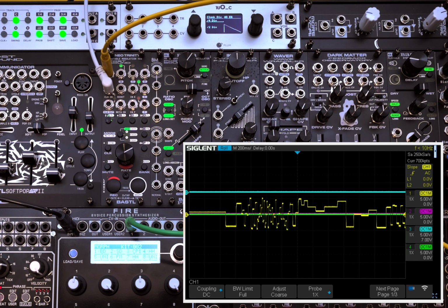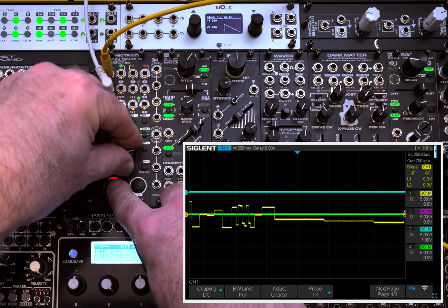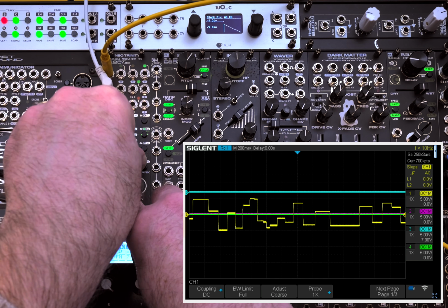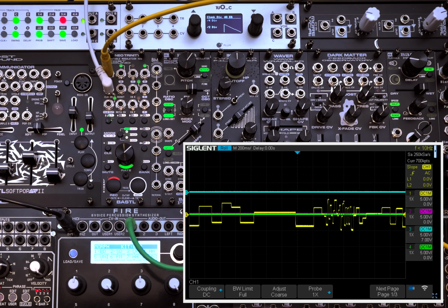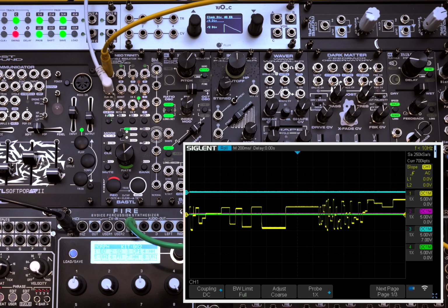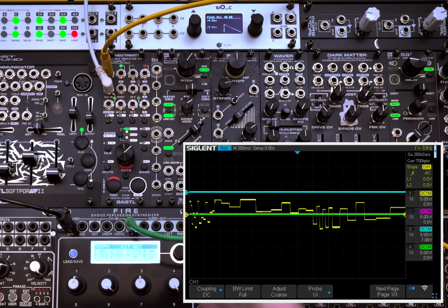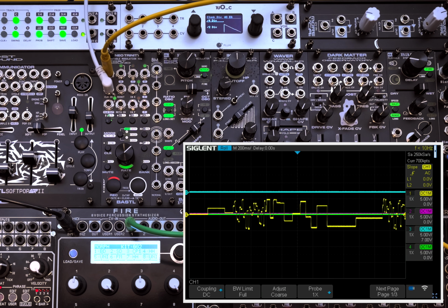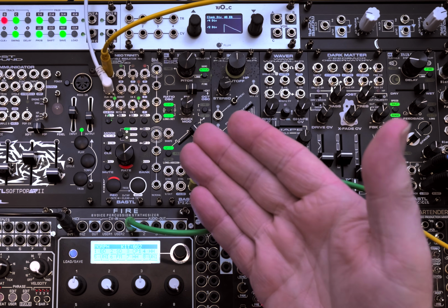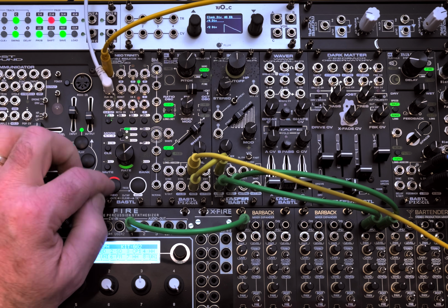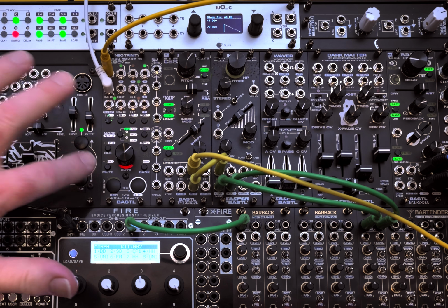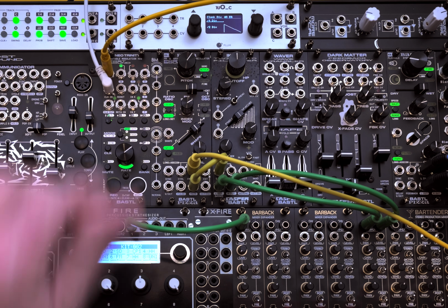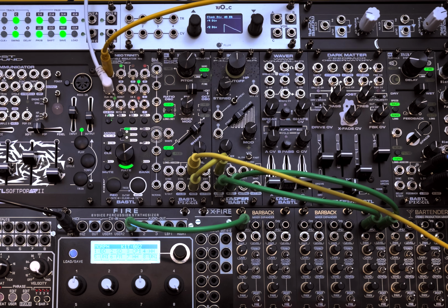Now you see there it's recorded my knob movement. And so I'm able to record knob movements, which in the case of an LFO, the knob adjusts the frequency of the LFO that's playing. Say I wanted to clear out the automation I've recorded, double tap on record, and you'll see the red light goes off, and now we're back to just free running against either the clock internally or the clock externally.